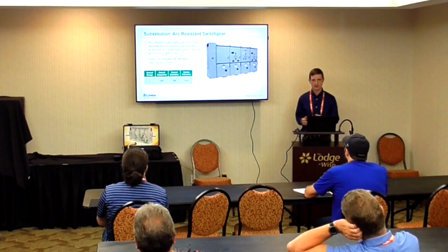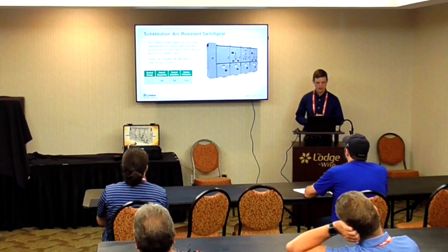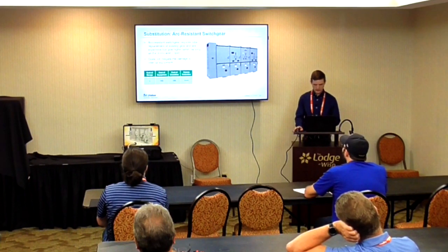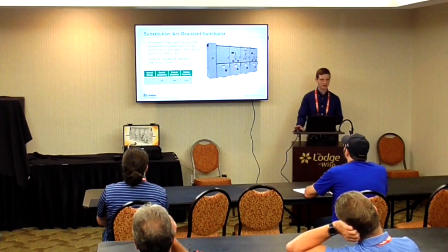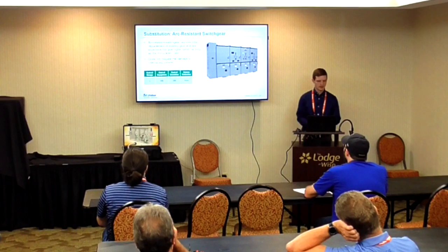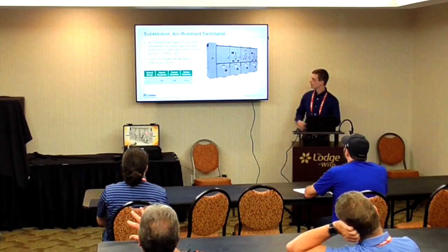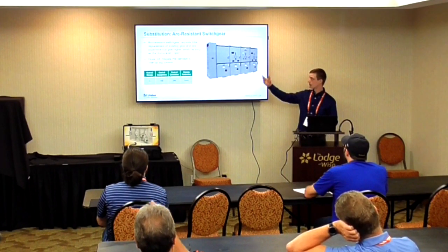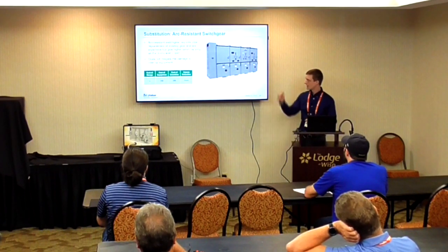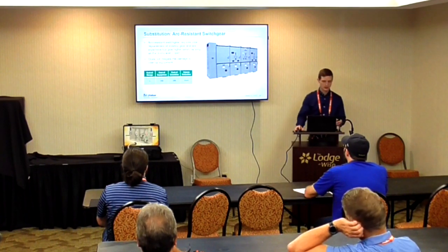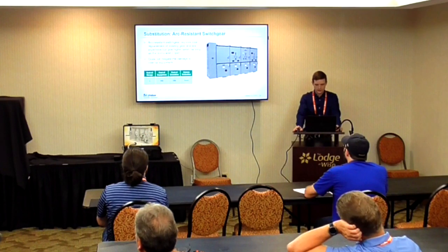So this is more of a risk mitigation and not an arc flash mitigation, which is substituting for the arc resistant switchgear. And essentially what's happening for arc resistant switchgear is the fault will still happen within the enclosure, but it'll be vented out either the side, top, bottom, or back. So it's just expelling that in another direction.